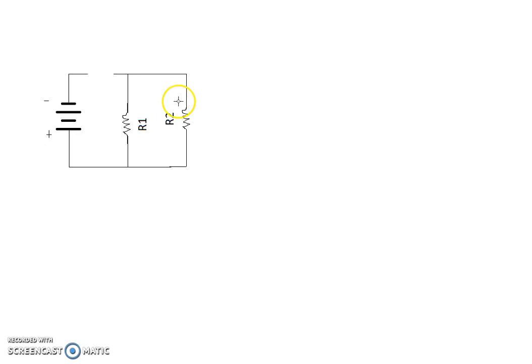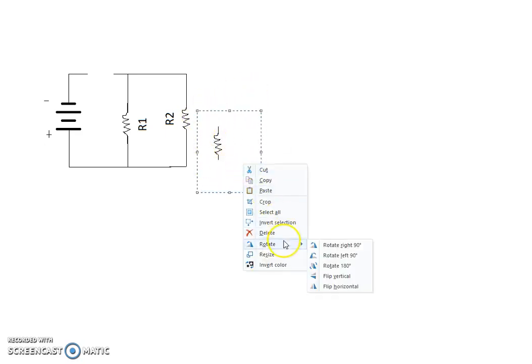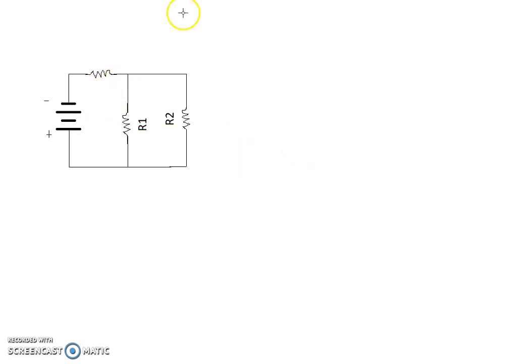Now what we can do is take another resistor, and you know what we're going to do? We're going to add that in series with these. And let's just call that resistor 3. All right. So all that has happened is we take the parallel resistance and then we add in the series resistance. So if this was 6.67, let's say resistor 3 is, I don't know, 30 ohms. Then we have 36.67 as our total equivalent resistance. And then we can apply Ohm's law to determine what the current is that's actually traveling through this battery. So you have some excellent examples here of the most basic series, parallel, and combination or network circuits.